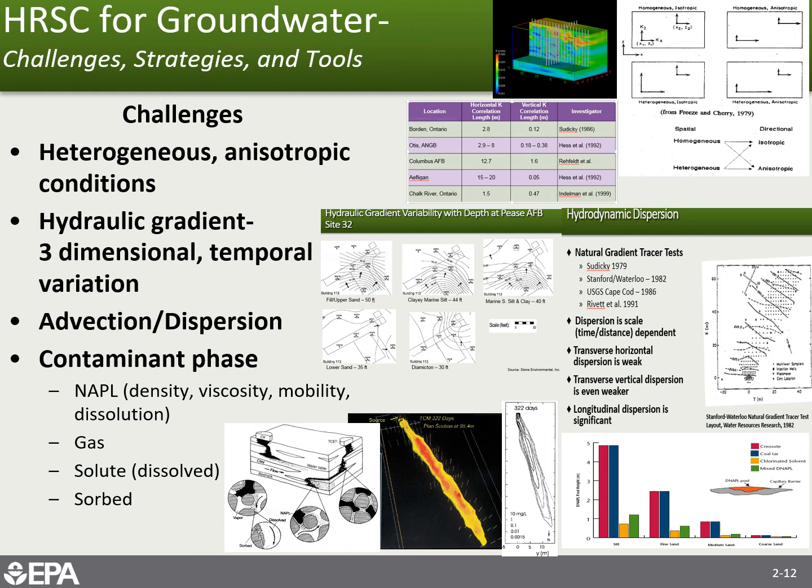So the plumes don't necessarily, under the influence of any other force, spread out through dispersion into these large shaped plumes, but actually, like the research from this example in the University of Waterloo showed, they can maintain these very long, thin, cigar-shaped plumes, and actually dispersion along the axis of the plume can be significant, so that you can see larger dispersions in the concentration gradients, for example.